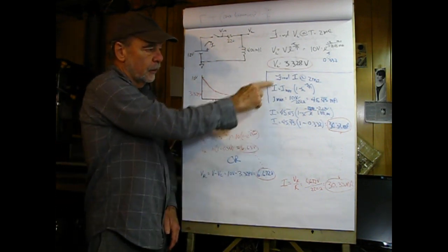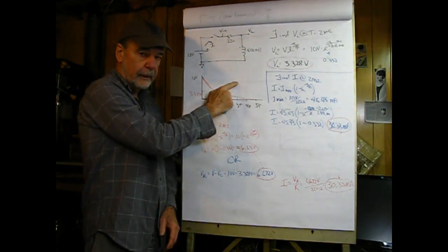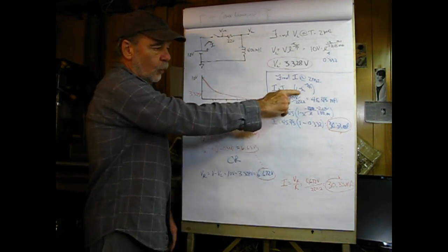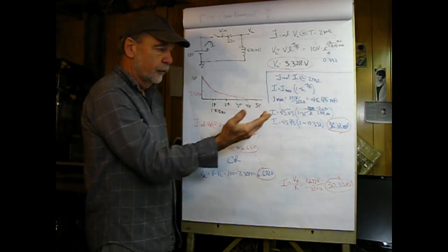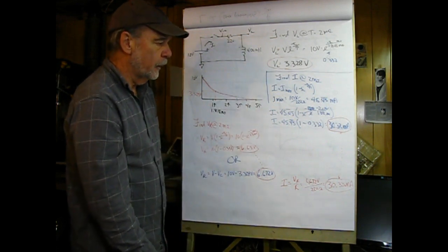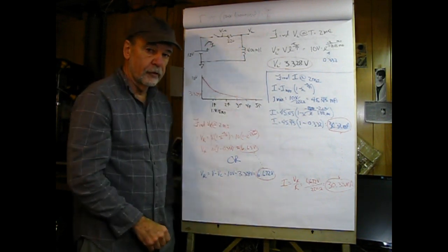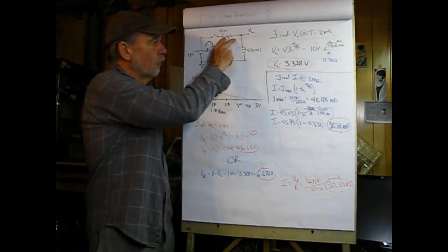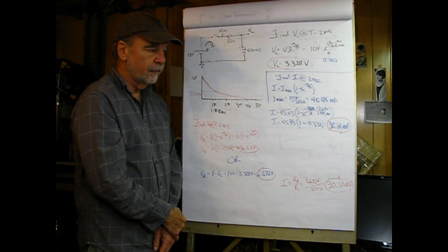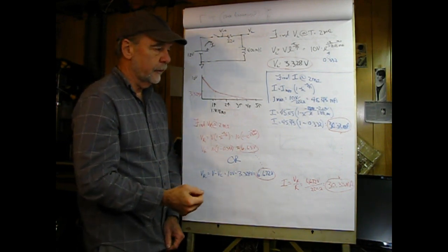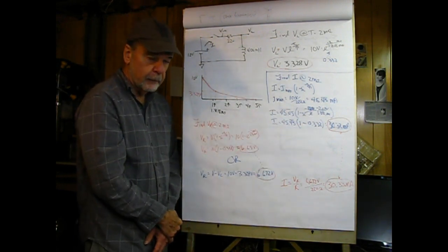So let's find the current at 2 milliseconds. What we know about the current from the previous page is that it's a rising asymptotic relationship, so here we have the 1 minus e involved. Substituting in our values, first we need to know what Imax is. In an inductor, after 5 time constants, the voltage across it is considered to be 0 volts. What that means is all of the voltage is across the 220. Therefore, we can simply use Ohm's law and determine that the final current, the maximum current that can flow in the circuit after the inductor is completely fluxed, is 45.45 repeating milliamperes.